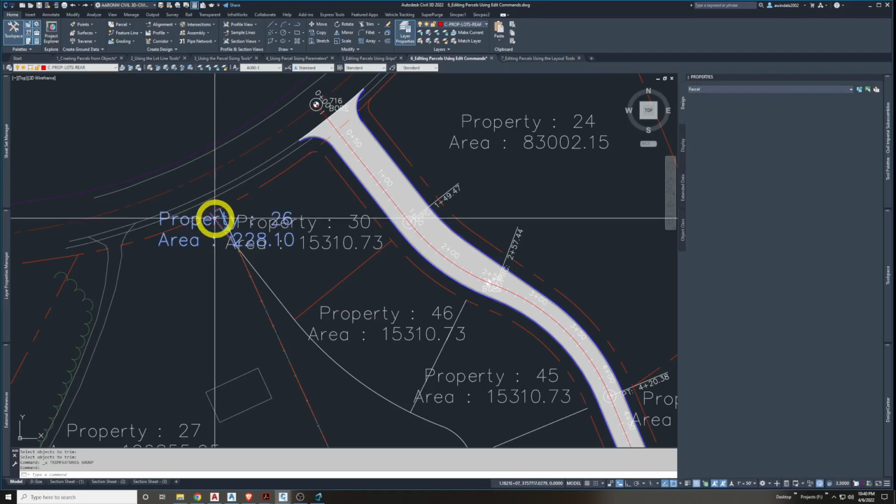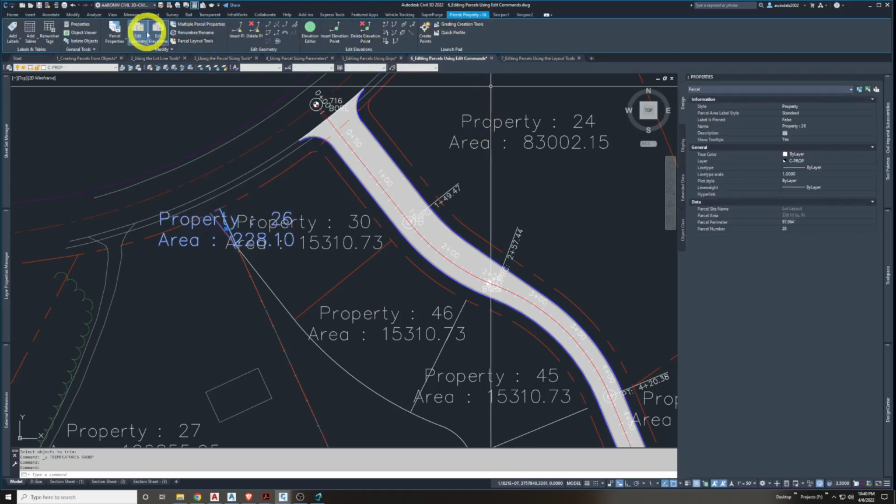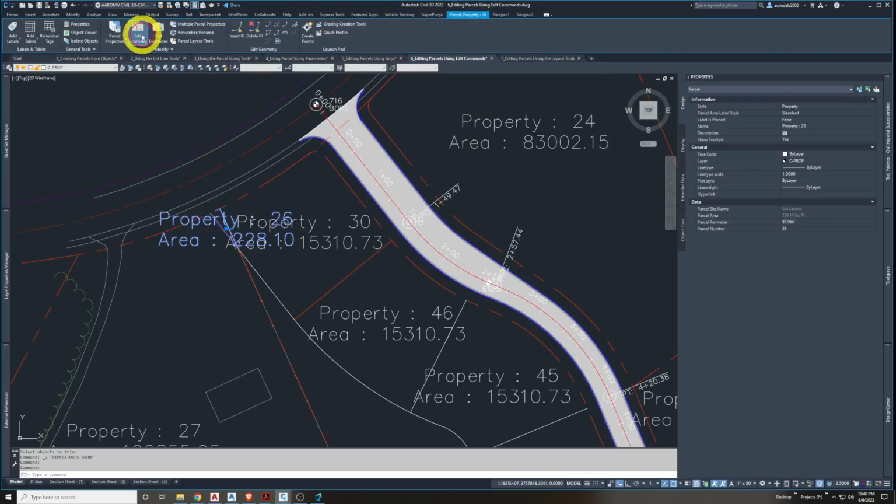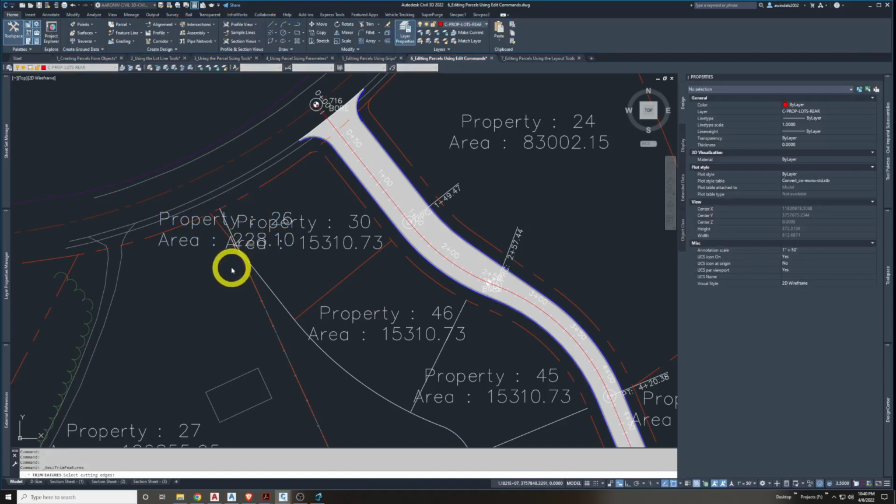Let's select the property. My contextual ribbon comes up. Make sure these are turned on. In this case, you just need the horizontal, but let's turn them both on. We'll go to trim, and let's get our cutting edges, what we're going to cut about, which will be this fence line it's saying in the book. Also do a lasso like that. Let's hit enter to accept that as my cutting edge.